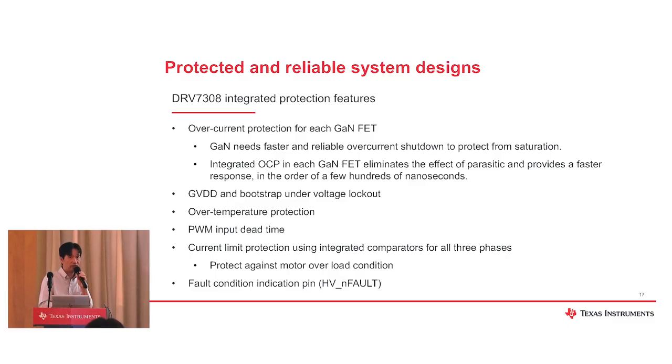Besides the switching features that the GaN DRV7308 offers, it also has integrated protection features. It has overcurrent protection for each GaN inside the chip, and we have VDD and bootstrap undervoltage lockout, over temperature protection, input dead time, and current limit protection using the integrated comparator for all 3 phases inside.